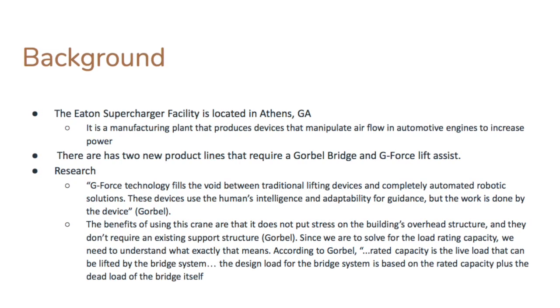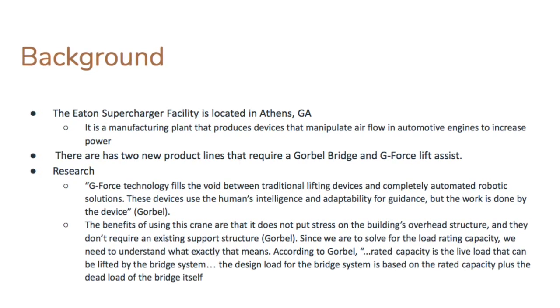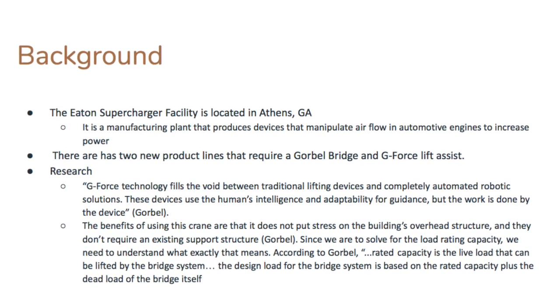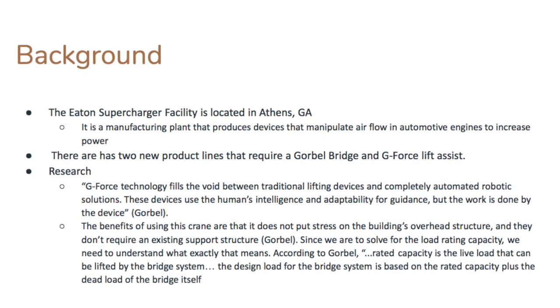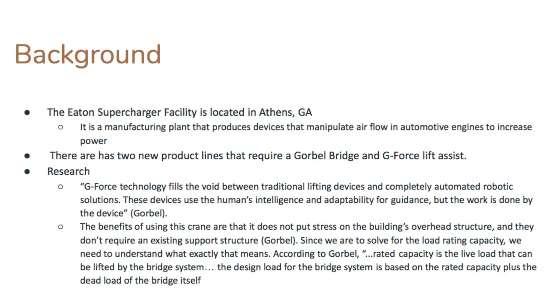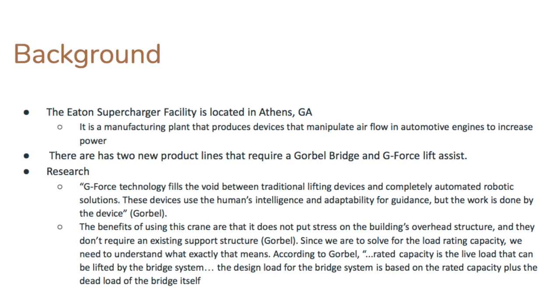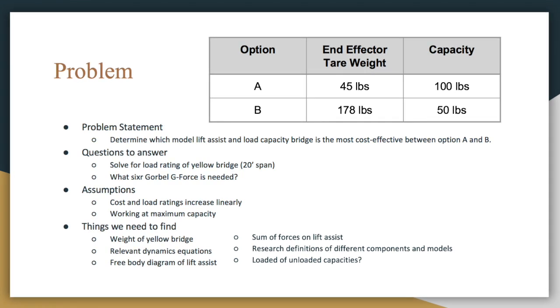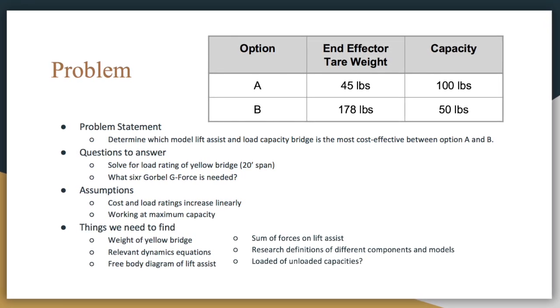Since we are to solve for the load rating capacity, we need to understand what exactly that means. According to Gorbel, rated capacity is the live load that can be lifted by the bridge system. The design load for the bridge system is based on the rated capacity plus the dead load of the bridge itself.